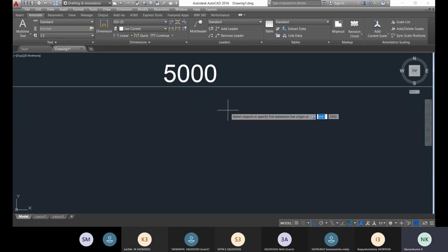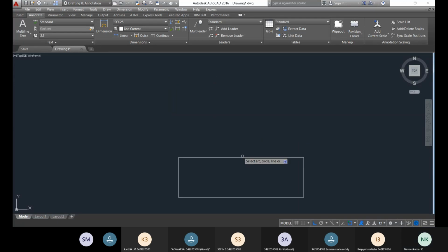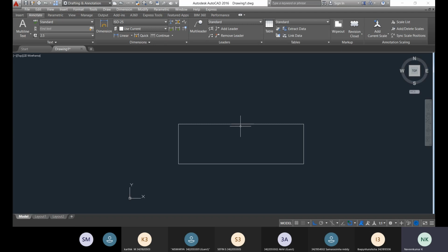If you want to zoom the drawing, you can scroll the cursor upwards so that it is maximized. This is also a shortcut for zoom: you can type zoom, enter, and all, enter, so that your drawing appears on your screen.